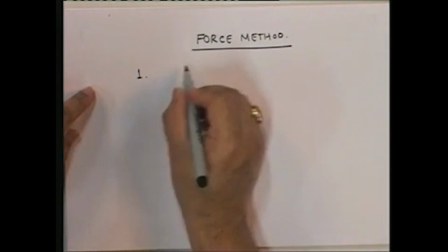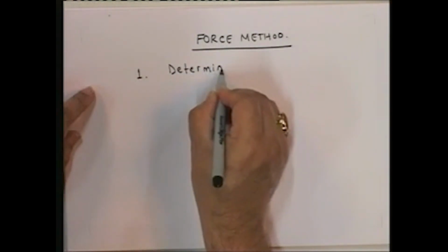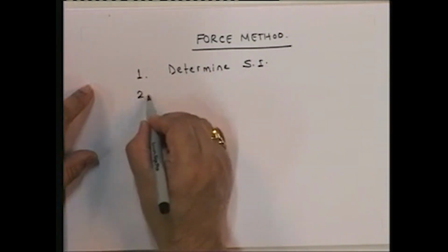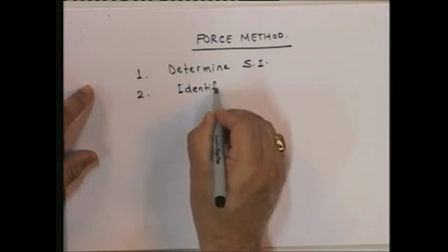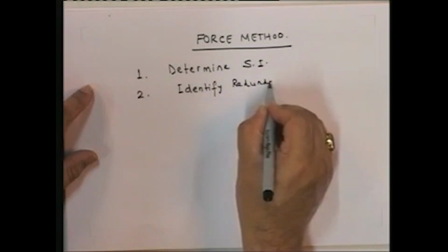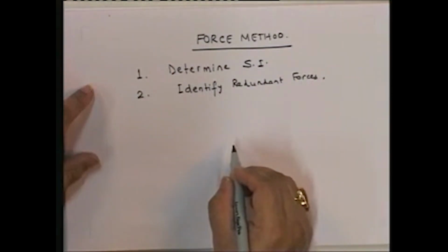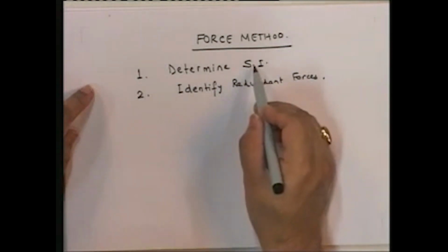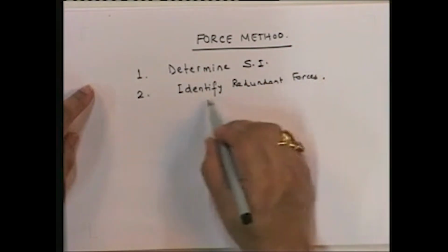One, determine static indeterminacy. Two, identify redundant forces. Now, how many redundant forces? Well, whatever is your static indeterminacy, you need to identify that many redundant forces. What do you mean by redundant forces?